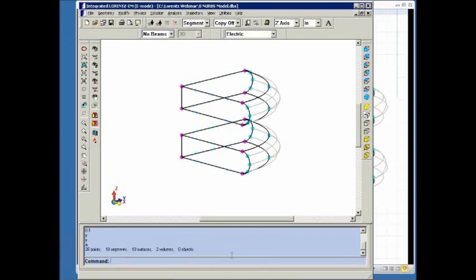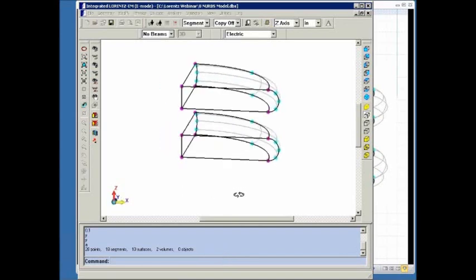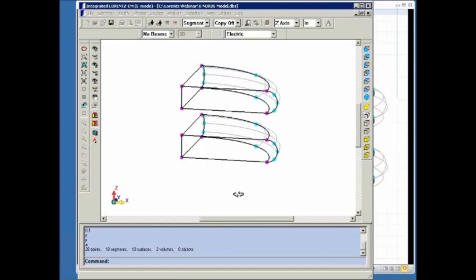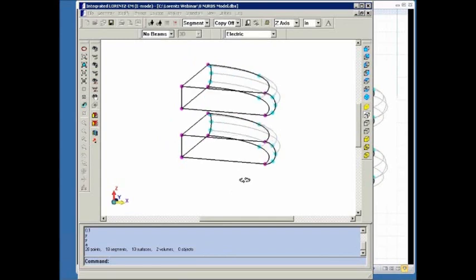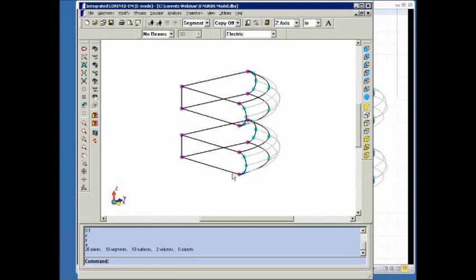Now, you notice all the line segments, or the NURBS that were consisting of straight line points, have been converted to line segments, but none of the arcs were. And that's because, as I said, I created this model by artificially breaking up the arcs into a series of points, and the resulting points don't quite fall within that 0.1% tolerance. So I'll run the command again using a looser tolerance.